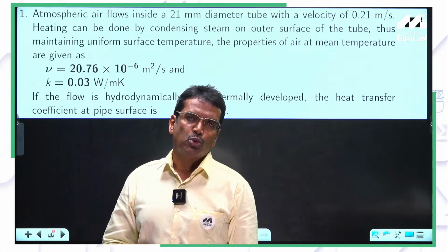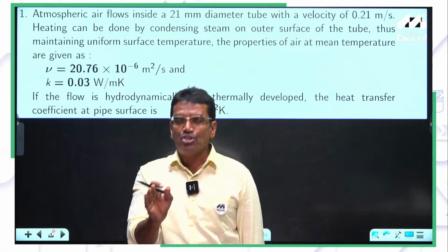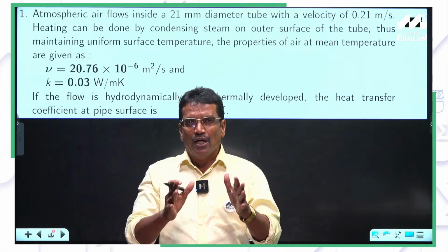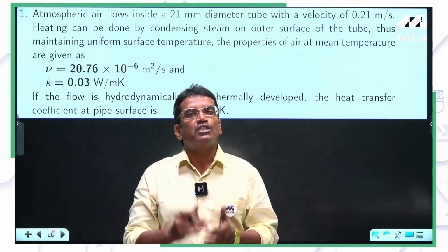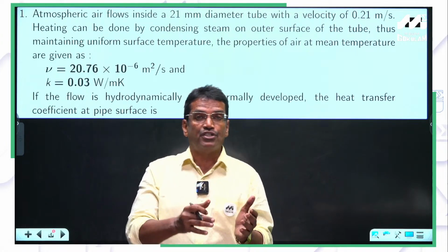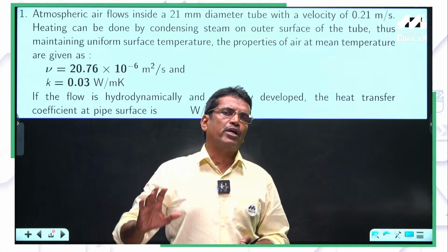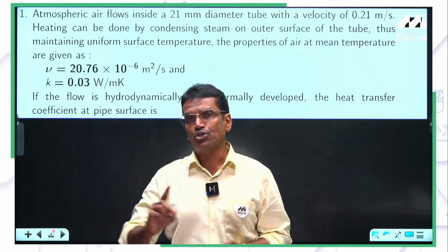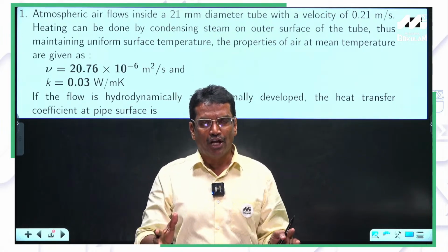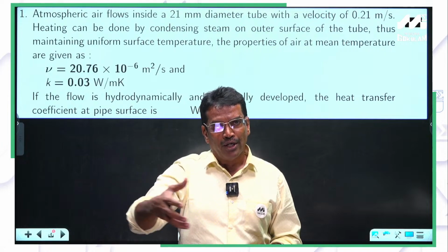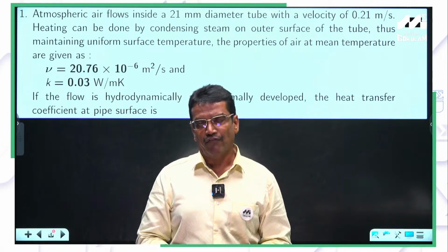Generally students feel convection is tougher, but if you prepare strategically, convection is the easiest chapter. When discussing convection questions, first of all we have to decide whether it is free convection or forced convection. Above 90% of the convection questions in GATE are from forced convection, where you will definitely be given some velocity for the fluid. How do you decide it is forced convection? Whenever a fluid, such as a cold fluid, is moving on a hot solid body, forced convection heat transfer is expected.